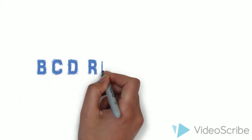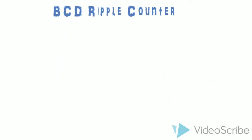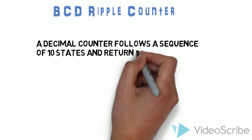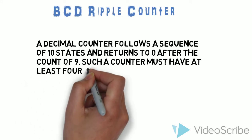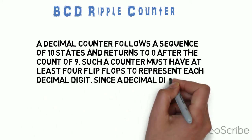Now the BCD ripple counter. A decimal counter follows a sequence of 10 states and returns to 0 after the count of 9. Such a counter must have at least 4 flip-flops to represent each decimal digit, since a decimal digit is represented by a binary code with at least 4 bits.